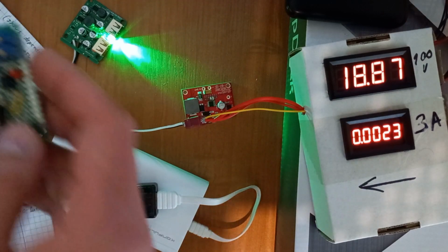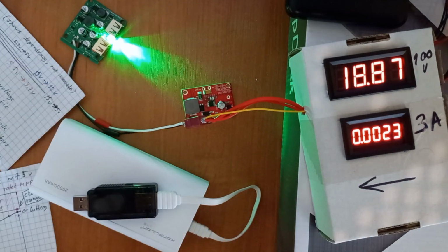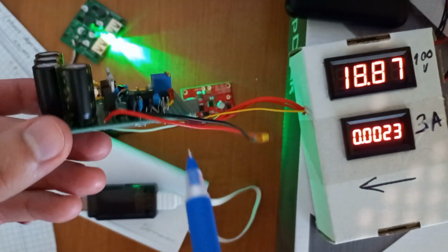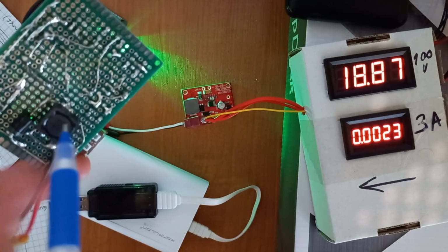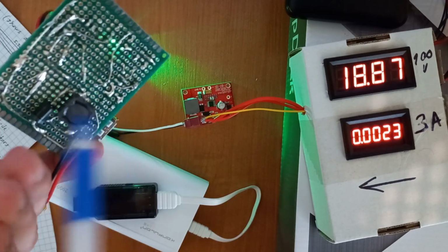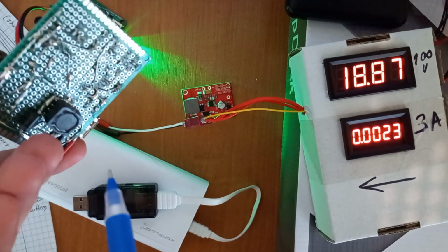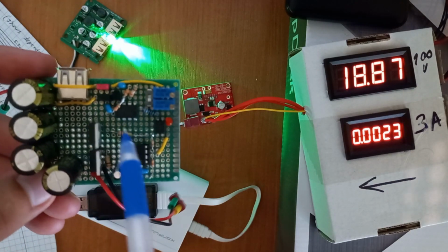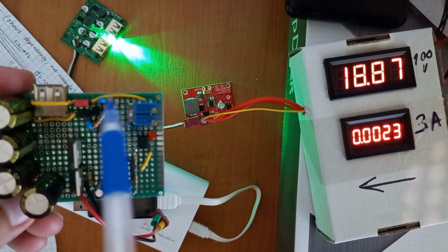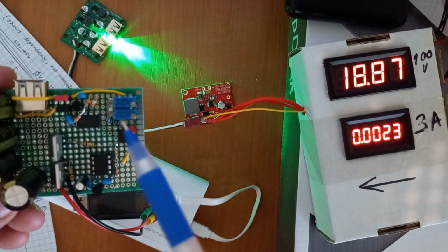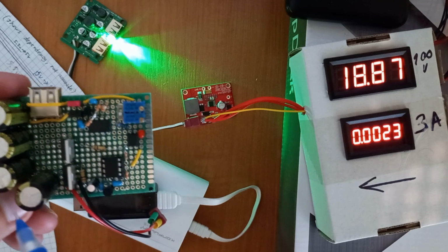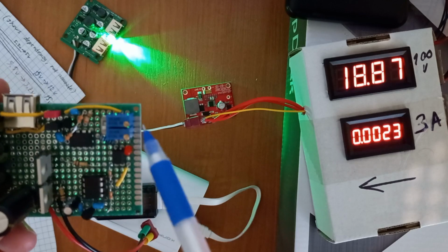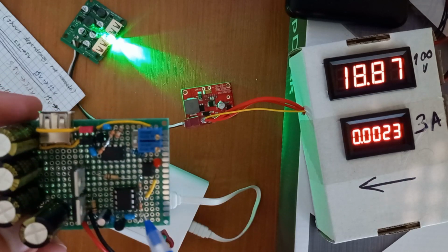Now some PCB notes. Here are the main parts, this main part with the inductor and diode on the opposite side. It was just more comfortable to assemble this way. Then the feedback part. This is the feedback part to stabilize voltage and to limit output voltage. Two voltage configurators and a selection switch. I just use it for comfort.